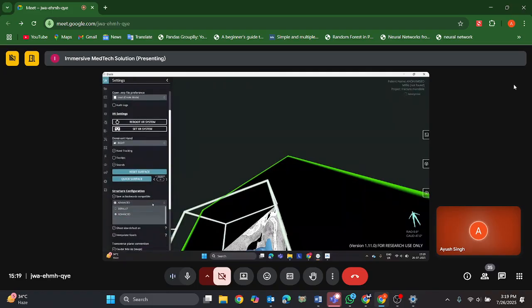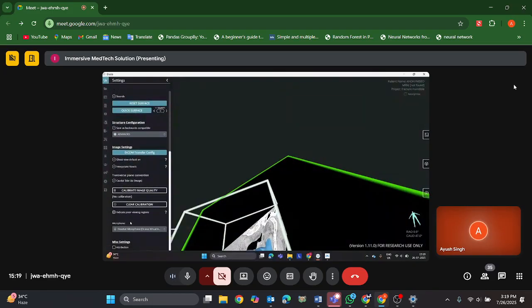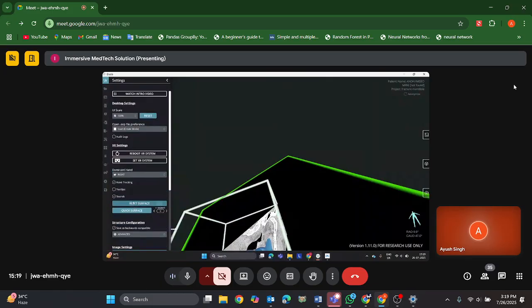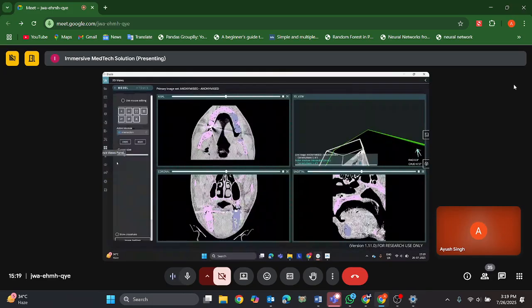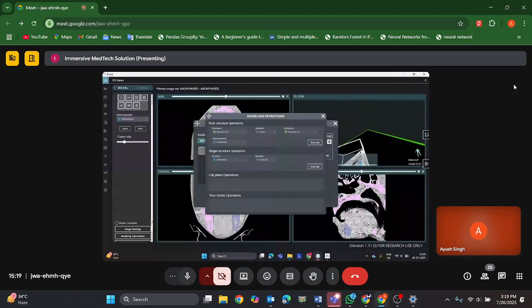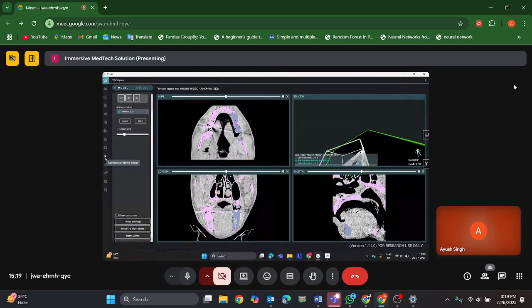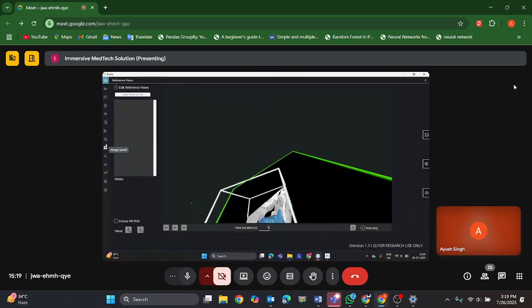We also have some advanced options while exporting. We can select our particular image file type, and if we need to increase the number of triangles, that can also be done. So the settings can be there. We select particular operations and then we can set the number of triangles. We require a very high-detail data model for a specific part.